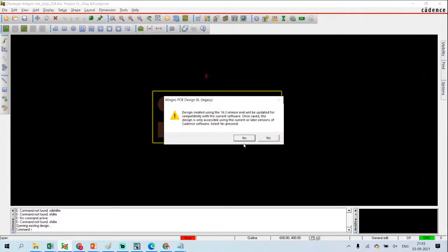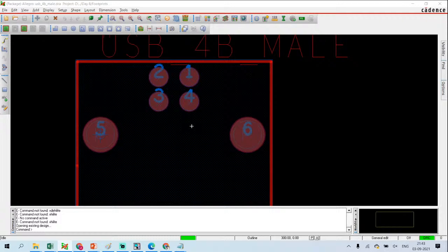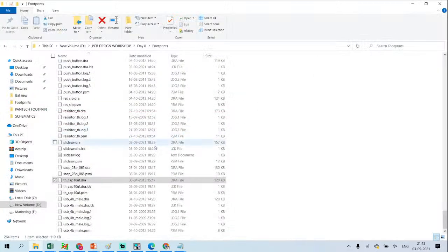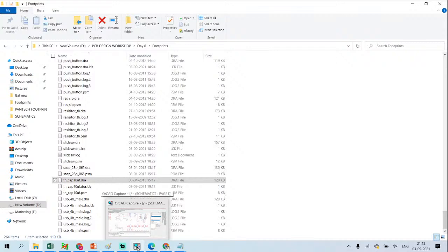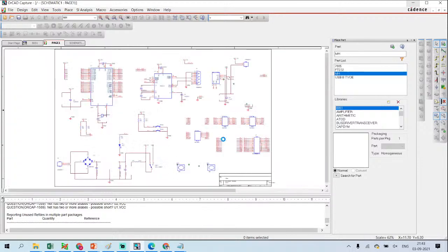Okay, so the USB footprints, and every footprint is there. So you could check this file. You could create the schematics, and once you create the schematics, link all those footprints to the schematic file and generate the netlist. Once you generate the netlist, it could be imported into the PCB editor, and we could place the components and route the board. Okay, so I'll take the questions.